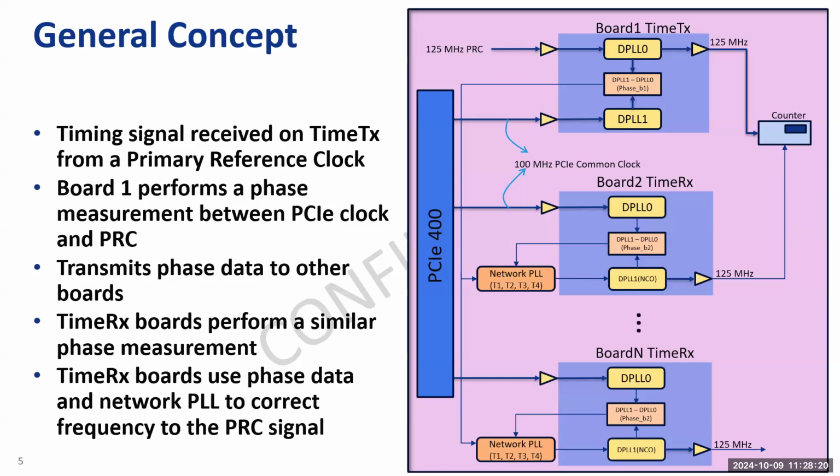So like I said, the use of spread spectrum being able to be on and off is a requirement as part of the PCIe standard. And so a lot of the testing you have to do both, because Intel requires you to test both. And there's requirements needed to be met. So that's all I'm highlighting, is you can't ignore it. I'm not arguing what was presented is not valid. It's just you have to highlight there is more investigation needed to understand the impact of the spread.